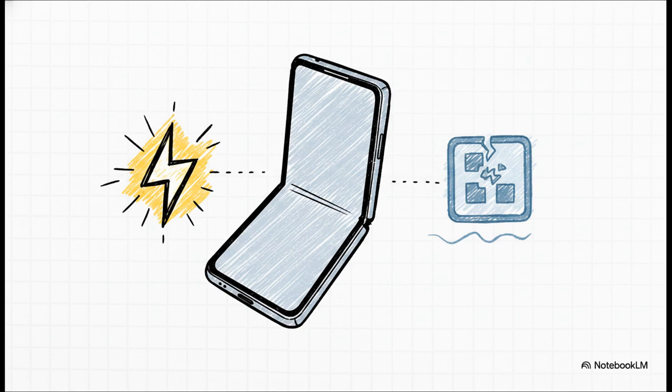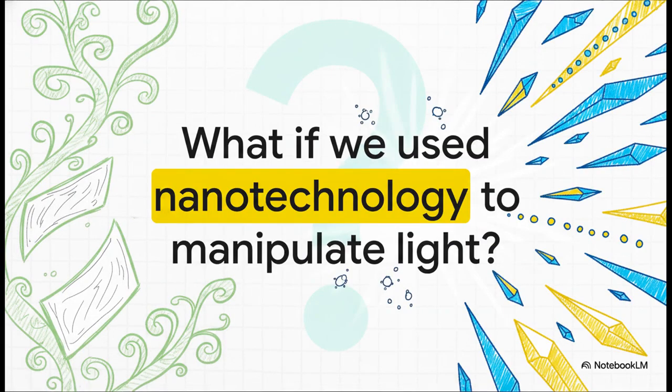But there's always a catch. Because the emissive layer is made of organic compounds, they can degrade over time. The blue OLEDs in particular age faster, which can sometimes lead to that annoying image burn-in. So organics are phenomenal for ultra-high contrast flexible screens.